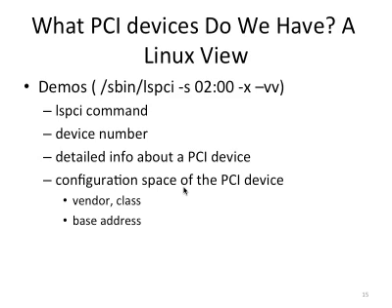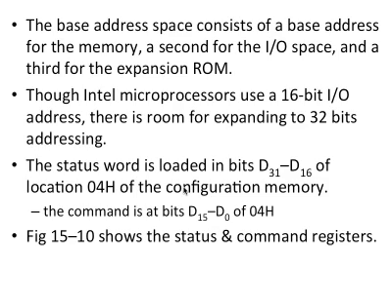So we just saw the example of the actual PCI devices present in the system, and we looked at their configuration bytes to figure out how the OS will understand what kind of device it is. This is to explain again the base address. The base address could be an address in memory or an address in I/O space. It's differentiated by using the least significant bit of the bar register. Typically, Intel architecture uses a 16-bit I/O address space, but there's room for expanding to 32-bit I/O addressing using these bar registers.